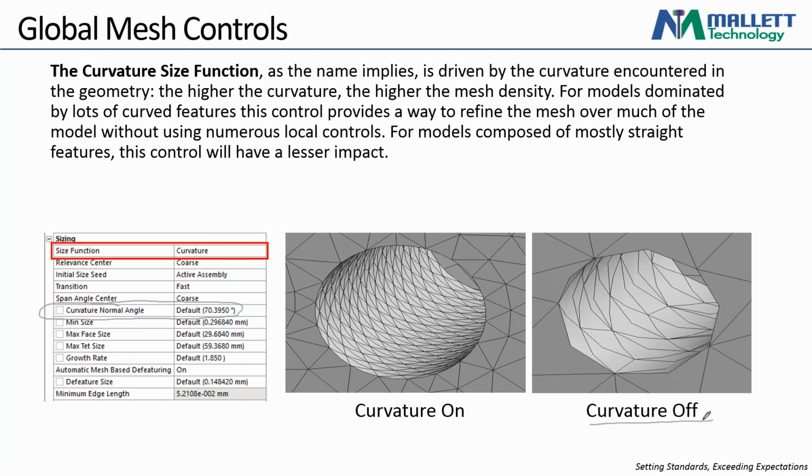You can see here, curvature is off in this case, curvature is on in this case. The right picture could actually be achieved with curvature on. You would just have, let's see, 1, 2, 3, 4, 5. So 360 divided by 5 would achieve this mesh coarseness. But generally, when I'm using curvature, I'm using it because, let's say I have a lot of sheet metal and I want broad spans of blank sheet metal to mesh much more coarsely than near holes, because I know that near a hole I'm often going to have a stress singularity, and I want the impact of that stress singularity to drop off quickly. So if I turn curvature on, I'm going to get finer elements around that hole, and so I can get a much better idea of what the stress is near that hole, assuming there's a bolt there or something.